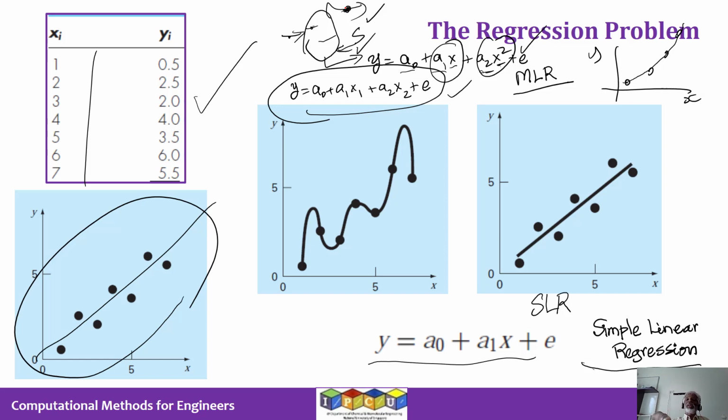So in this particular case, I can take the feed flow rate F as x1, I can take the steam flow rate as x2, and maybe I can take the temperature in one of the top trays in the distillation column as x3, etc., leading to a model where the top composition Y is, let's say, a linear function of the feed flow rate, of the steam flow rate, of the temperature at the top of the column, things like that.